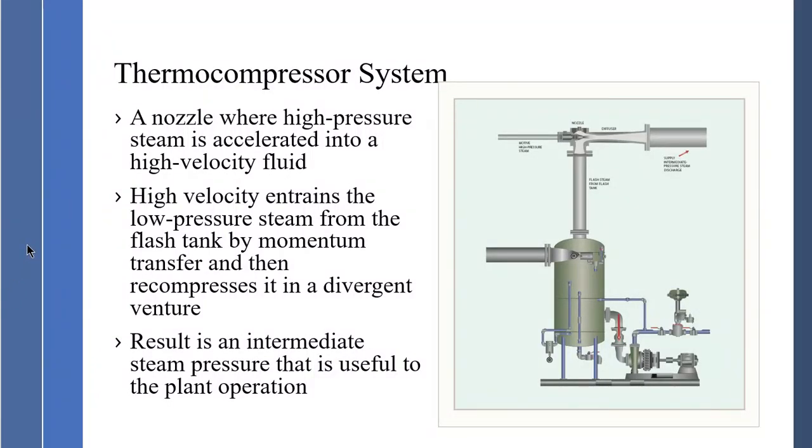Another diagram of the thermocompressor system here shows the high pressure nozzle. This is the motive steam coming in here, the low pressure flash steam coming up here, and producing the intermediate steam or higher steam pressure that can be used by other processes. It's a very simple device, very easy to install, and very useful to take low pressure steam and make it a more useful steam pressure.